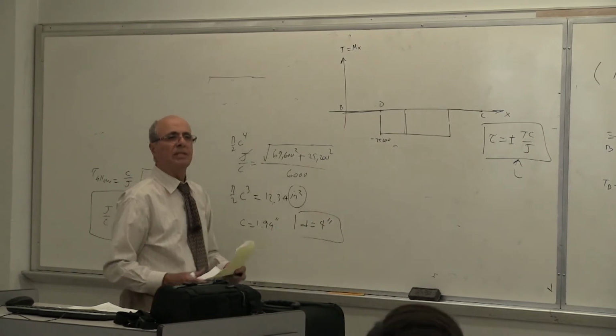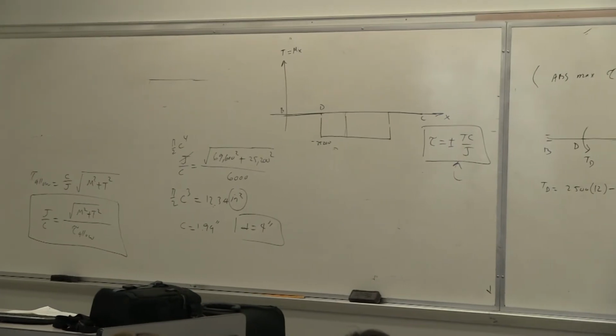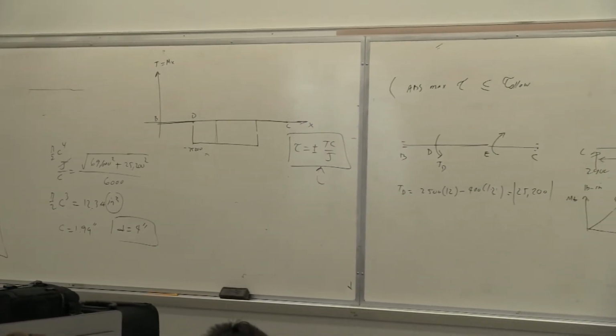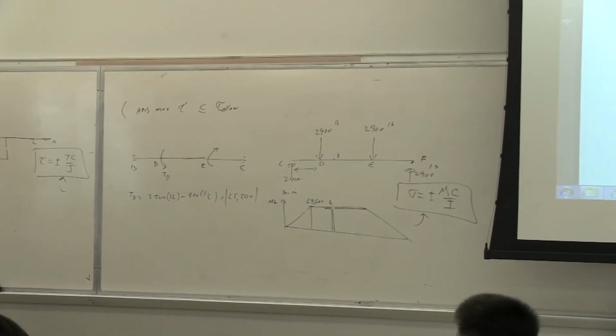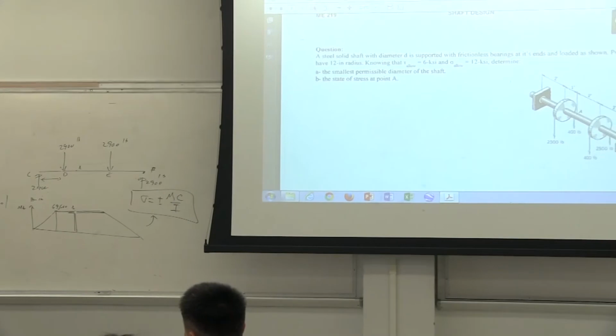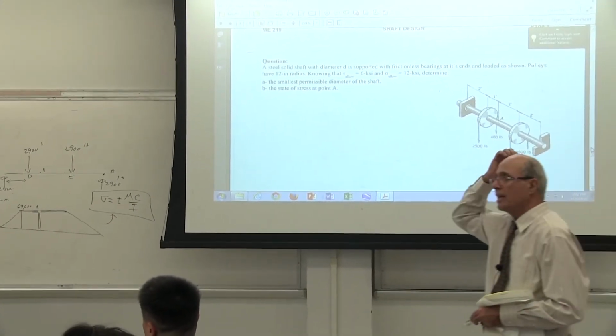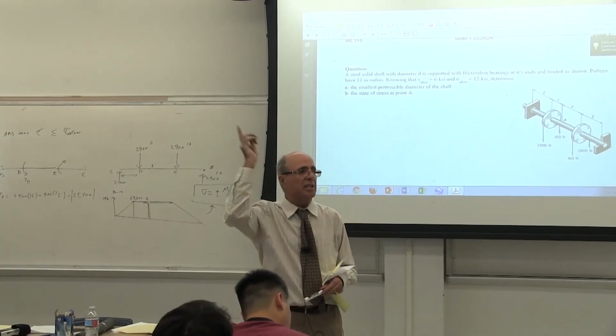So that would have been the answer without any trial, but it has gone through the Mohr circle. Everybody understand? It has gone through absolute maximum shear. It has gone through the theory of failure. Everybody understand? And we decided that here shear criteria is more important than normal stress, yes or no? And we designed the shaft immediately, one equation.